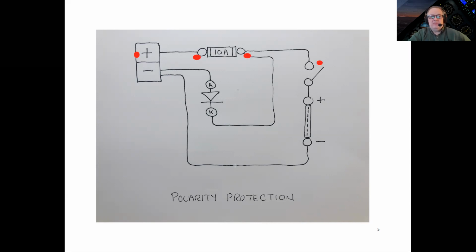Now, as you can see, because there's another line connected right here, power would have also gone through this line up to the cathode of this diode. Because that is reverse biased with respect to the source, no current would flow through there. So as soon as we close the switch, we would have power moving through positive to negative through the load and back to the negative terminal, and that would complete the circuit.